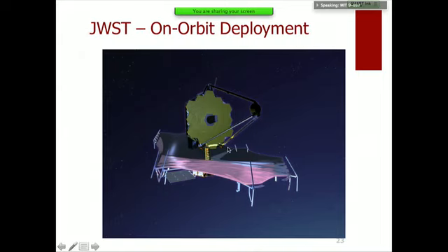James Webb Space Telescope. I'll send you a link through email. There's a simulation of this on-orbit deployment. It truly is amazing. This spacecraft will be launched in a box essentially, and the deployment sequence is very carefully choreographed. First, typically, you deploy your solar panels, right? Because you need power, because you're only running on battery initially. If your battery runs out before you've had a chance to deploy your solar panels and get fresh power into it, you're in big trouble. So typically solar panels first, then communications, and then you start deploying the other subsystems.